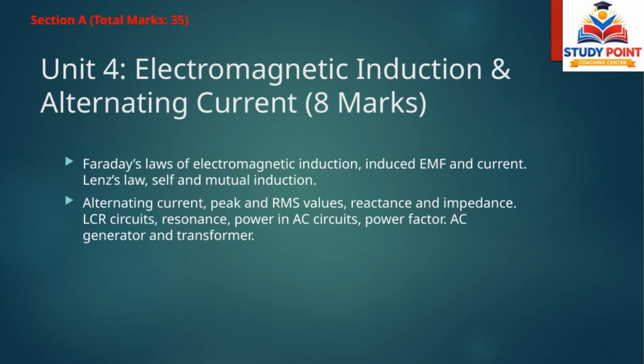We'll then explore LCR circuits, which combine inductors, capacitors, and resistors. These circuits can resonate at a specific frequency, leading to maximum current flow, an important phenomenon in tuning circuits. Power in AC circuits is another key point. We need to understand how power is calculated and the significance of the power factor, which indicates how effectively the